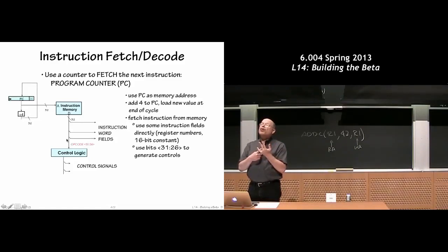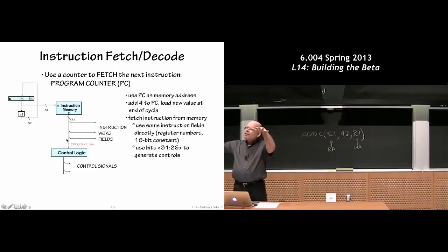Oh, you mean, you're thinking about the control signals that go into the ALU, which were 5 bits of control signal. And those will clearly be information that we're going to have to generate from the 6-bit opcode. But the opcode in the instruction is not the same thing as the ALU control signals. And we'll discover that the 5 ALU control signals are only some of the control signals that we'll need to generate from the 6-bit opcode.